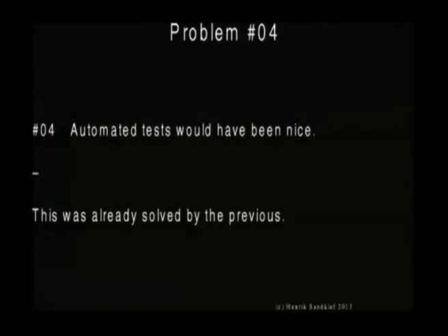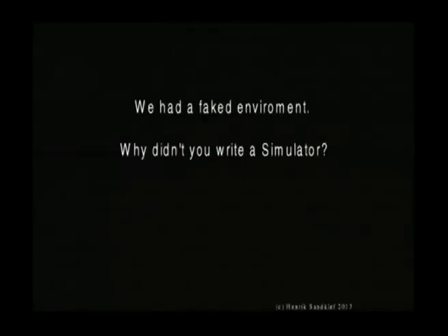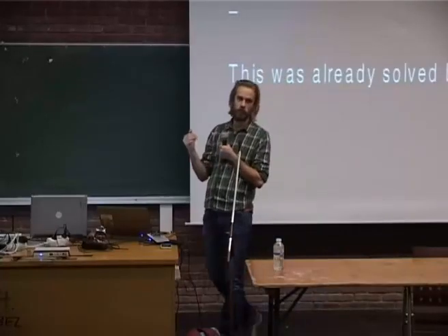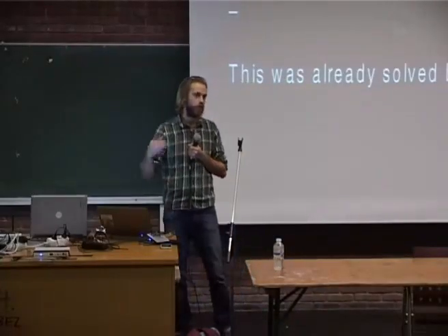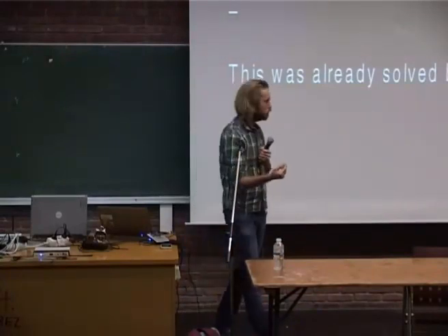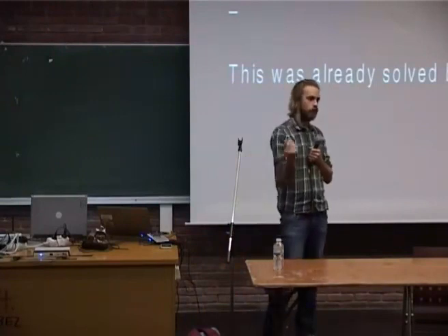And we also needed to automate the tests. So we realized that we had to write a sort of faked environment. Basically we took the Arduino API and implemented almost every function, the ones we use at the university, so we could create a program that could run by itself with no hardware.